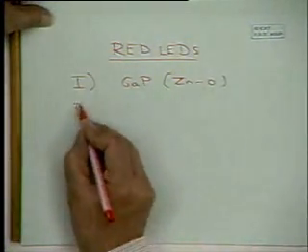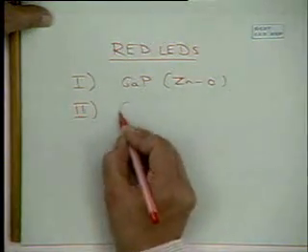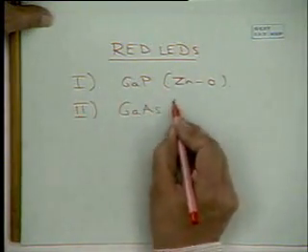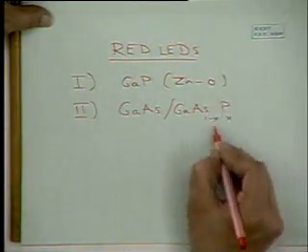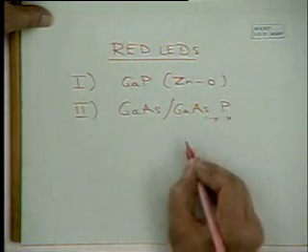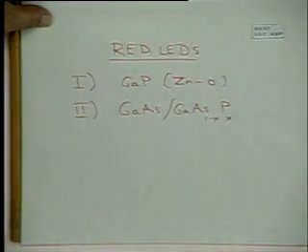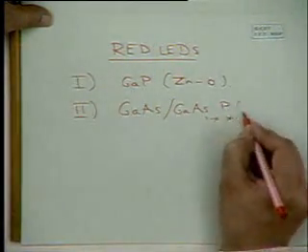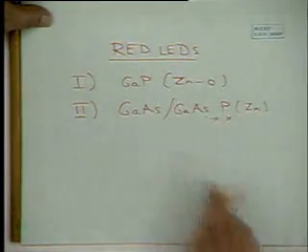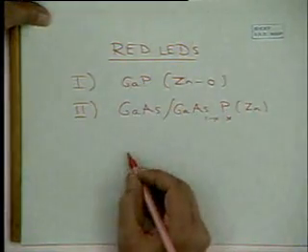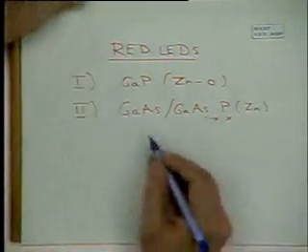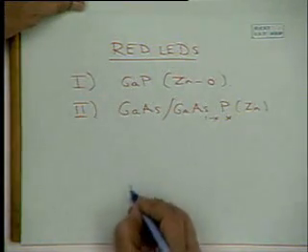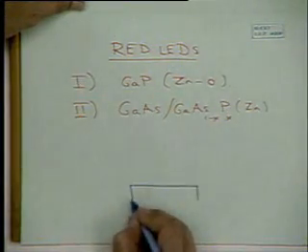If you remember, I said that historically the first type of LEDs was gallium arsenide phosphide, graded, and I can draw that. Obviously with zinc doping. What is the structure of this? I might as well discuss this now. Traditionally, this was the first. Why? Because gallium arsenide substrates were available, gallium phosphide substrates were not available.